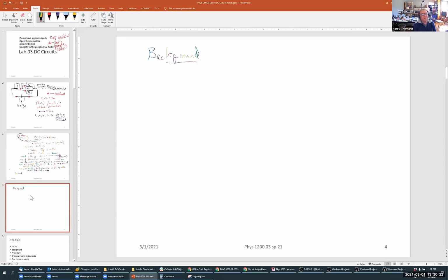Right. So this is where you do the circuit theory explicitly, right? The rules of combination. And really, the biggest thing from the circuit theory is you present the series circuit, and then you have the three rules, right? One conductive path, current is the same everywhere, and three, the voltages add up.